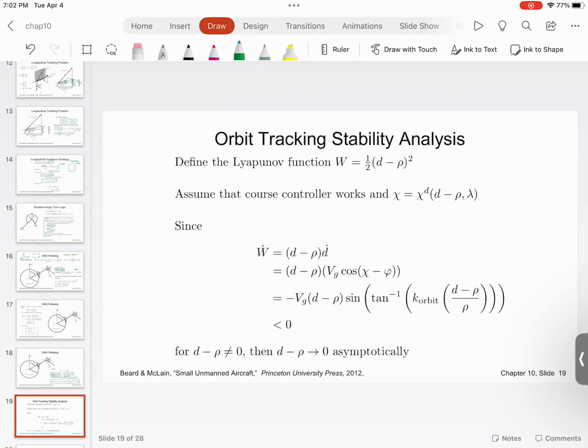To track that, you use the Lyapunov function type of approach. As you can see, you define this Lyapunov function, find the derivative of the Lyapunov function, and show that this derivative is less than 0, which means the controller that you have designed is stable. Now, believe it or not, the Lyapunov technique can help you build very cool controllers very quickly.